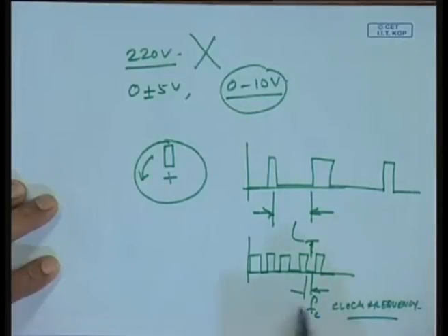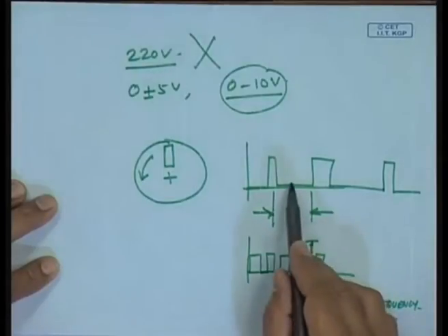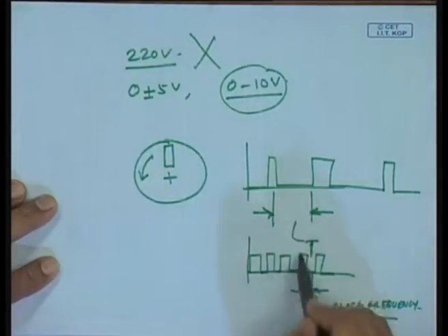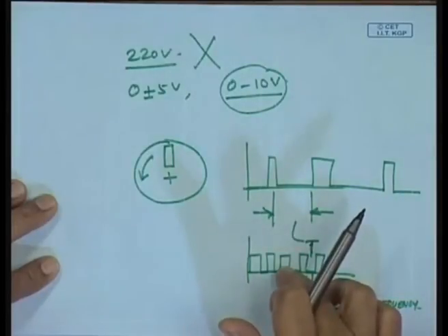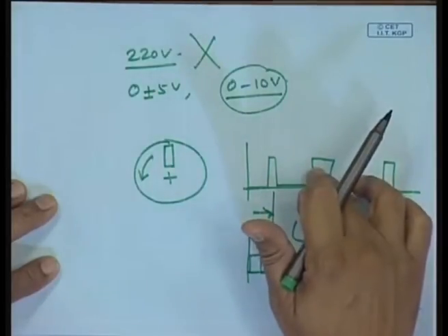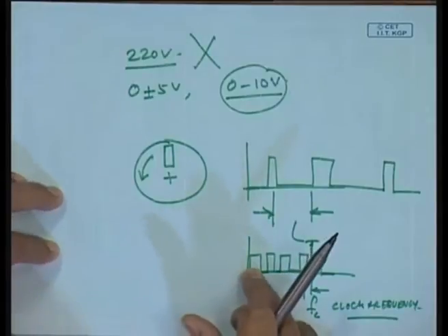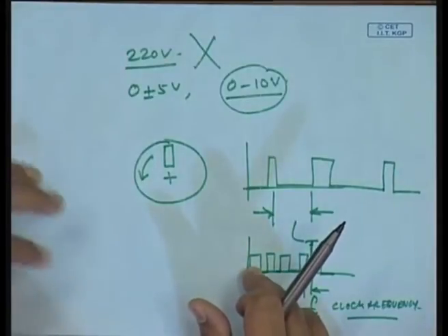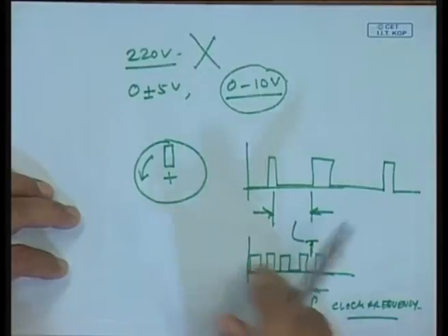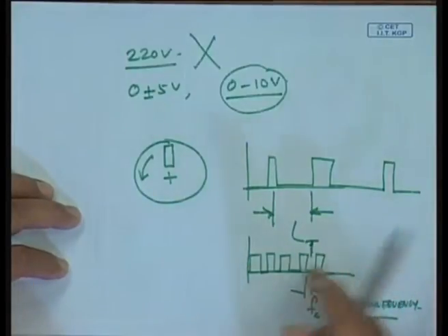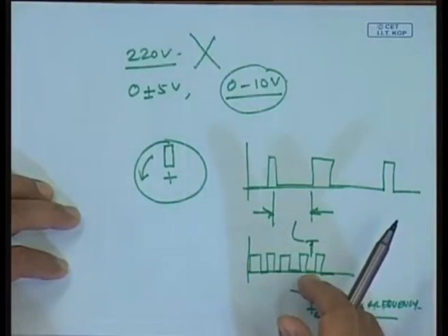So, I can compare this clock rate with the pulse actually measured, and then say, relative to this clock, what is this shaft's speed. So, this clock is given by an A to D which has a counter or a timer. And these are very high frequency clocks. When we talk about measuring using rotary encoders to capture phenomena from mechanical machines, I will go into details then.